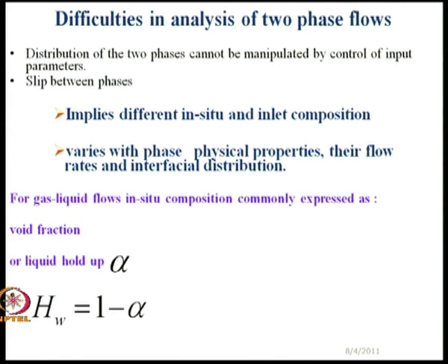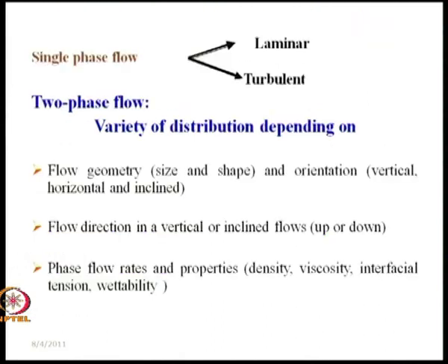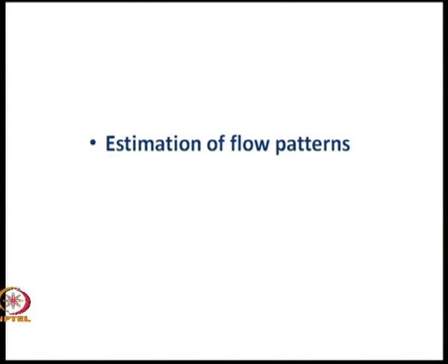Okay. So, therefore, since it governs the slip, it governs the heat, mass, reaction kinetics, it governs everything of two phase flow. The first thing which we should study is the distribution of the two phases and how the distribution varies with different phases. Say air, water, what are the different types of flow patterns which are available? Instead of air, if we use an oil, how the flow patterns change, how they change with flow rate, and definitely how they change with the conduit orientation, the conduit geometry and things like that. So, we will be proceeding systematically accordingly, and today we are going to start the estimation of flow patterns.